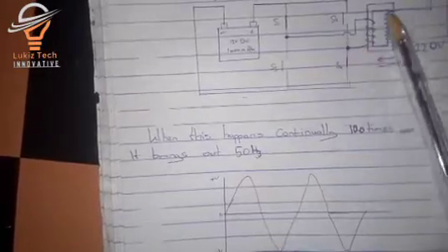So now let's see how the low voltage is now being stepped up. When the switching is being done repeatedly, we can add a step up transformer to step up the low voltage 12 volt AC from the switch to the 220 volt side. The transformer will step up the 12 volts coming from this switch here to 220 volts AC for the appliance.